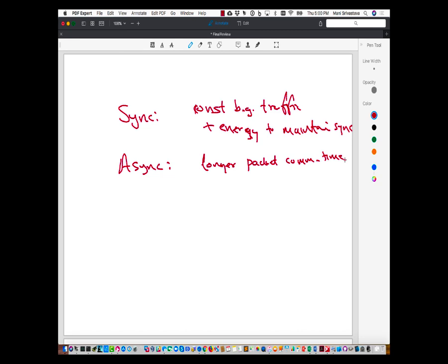Yeah, exactly. So if the data is going to be naturally more frequent, then might as well use sync, because in fact, if data is sufficiently synchronous, I may not need explicit synchronization packets. I can just make use of the data packets to opportunistically also synchronize, because synchronization is just some additional timestamp there. So higher rate scenarios, maintaining sync is the preferable approach.